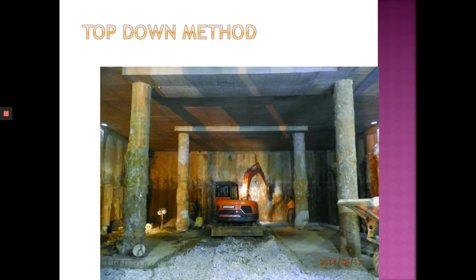Okay, then the third method for excavation of basement is top-down method. Now, I need you to really focus on this because it needs a bit of imagination. Okay? Top-down means you construct the basement from the top to bottom. Just now, I explained for the open cut and cover, you build the basement from the bottom to the top. Okay?